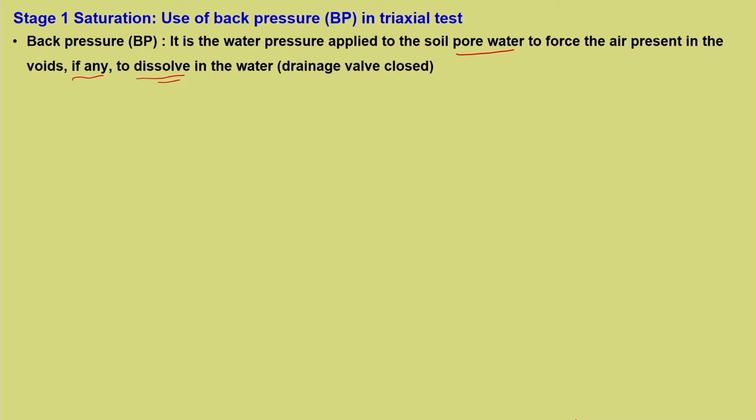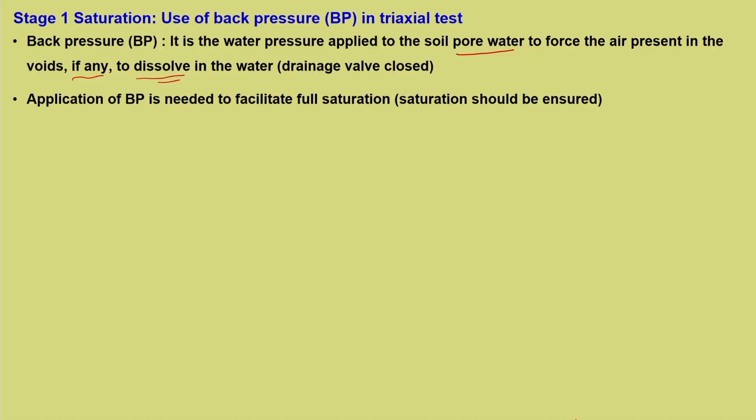Please make a note, this process is without changing the effective stress condition or the initial state of the sample. Only what is happening is the air which is present dissolves into the water and gets displaced by water. So, water displaces the air and hence it achieves complete saturation, which is a condition mandatory before consolidation or loading.